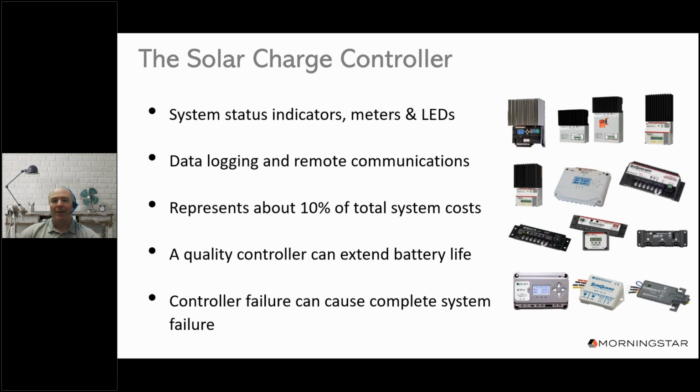Reliable charging to maintain battery health and extend battery life is affected by how well and also how fast the controller software controls the electronic component hardware. Battery and PV voltage and current can change in split seconds, and the power electronics have to be able to respond fast enough. Most people don't see these dramatic swings going on within their controllers and inverters, but if they did have scopes and sophisticated monitors that could show what's actually happening, they could tell which controllers are going to have the best effect on battery life.